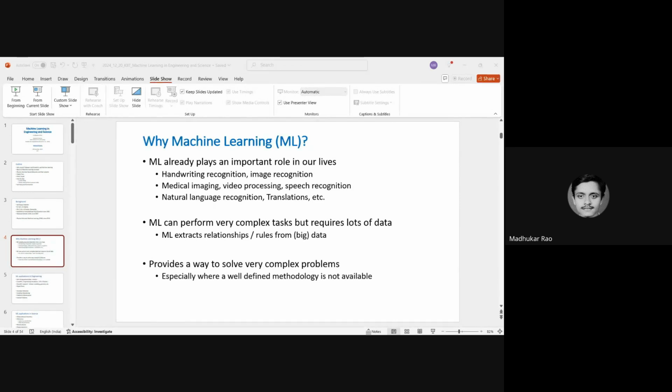And I have only 5 data points for slug flow, but for bubbly flow I have 1,000. So that is unbalanced data, and therefore we must do stratified cross validation to make sure we don't miss out any. If you divide it equally, you'll probably end up missing out some important data points.